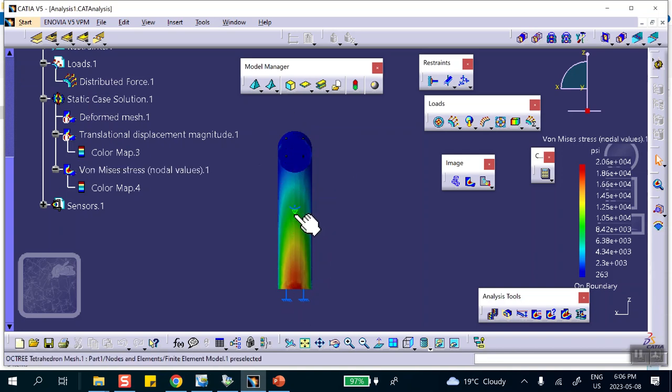They stay on that vertical cut plane. And that's what we call a roller condition. CATIA does not call it roller, it's called surface slider. Roller or surface slider is a fancy way of saying that points on that plane do not penetrate it, do not go to the left or to the right, they stay on that plane. That's what we mean by symmetry, which is a big thing in this course. All right, folks.